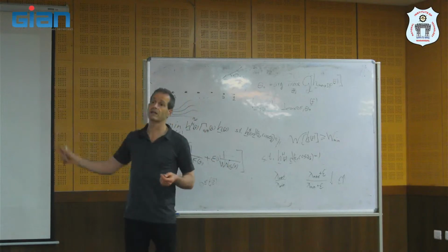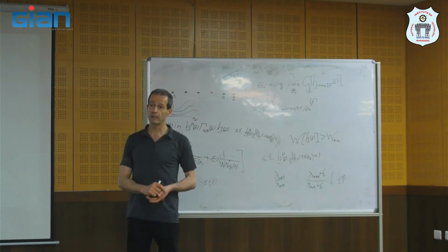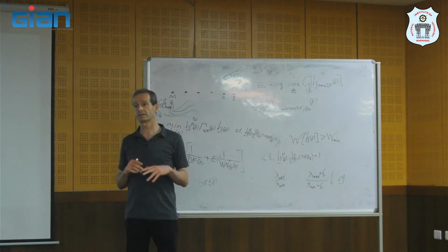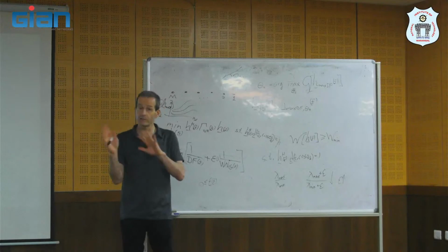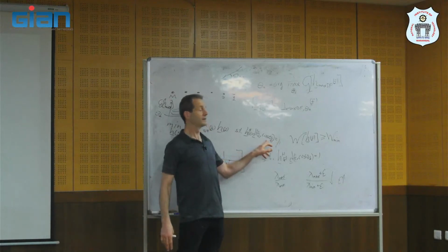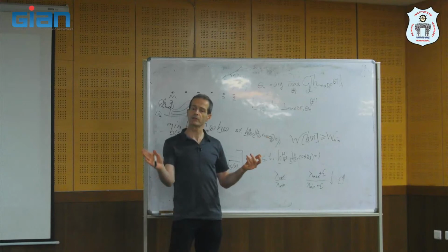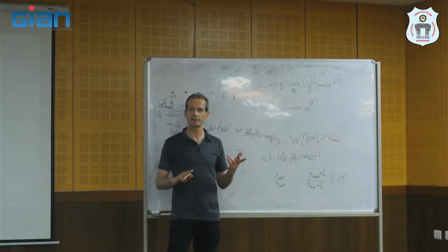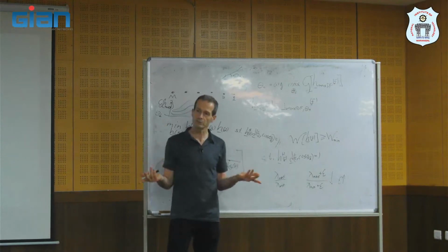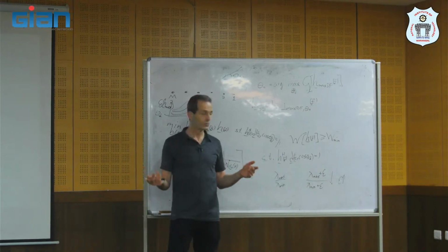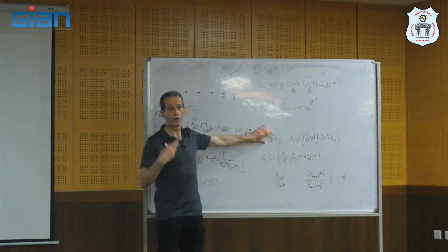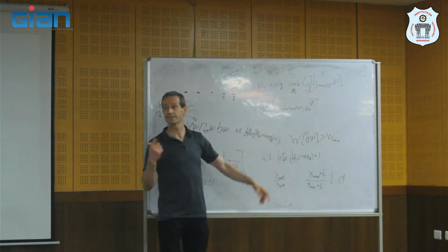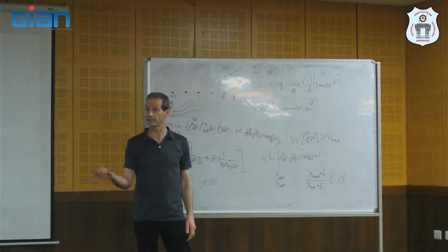So we will talk about null steering. It's a very practical way, as long as we know the direction or we can estimate it. And if we don't know these directions accurately, theta d, because we estimate it online, or we estimate the direction of interference and don't know them accurately, what do we do? We design beamformers that are robust to these errors. This is called robust beamforming.